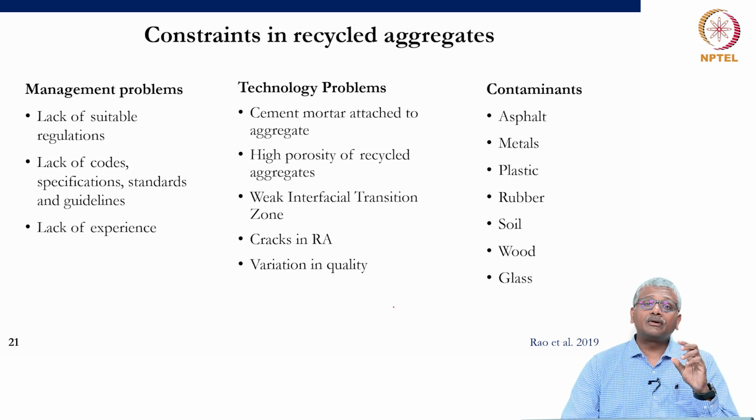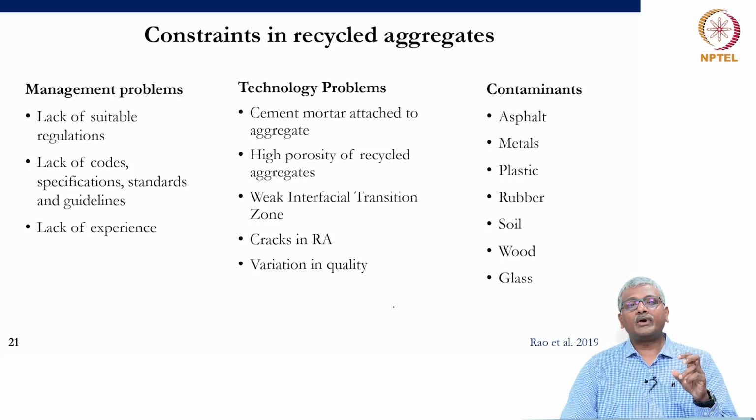What is the extent of porosity that is increased when this cement mortar is attached to the surface? Because of this mortar that is attached to the surface, there will be a weak interfacial transition zone that will lead to planes of failure that happen within the concrete, and cracks within the recycled aggregate because of the crushing process that can also lead to much faster failures.